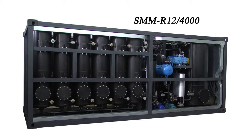As an alternative to the existing oil regeneration process, GlobeCore offers equipment based on percolation regeneration of transformer oils with fuller's earth. This technology has the following advantages as compared to the existing ones. After regeneration, physical and chemical parameters of the oil, such as tangent delta and acidity, exceed those of fresh oil.